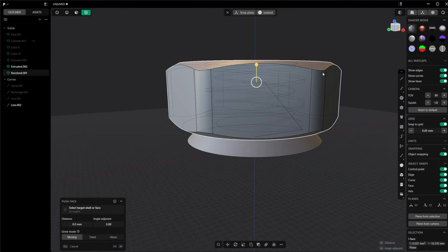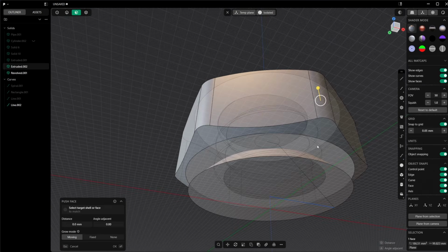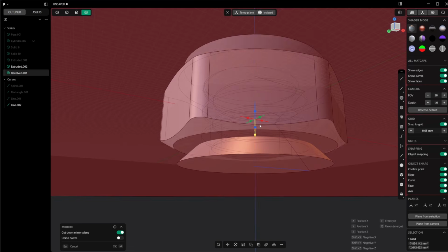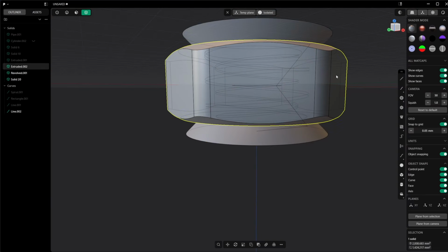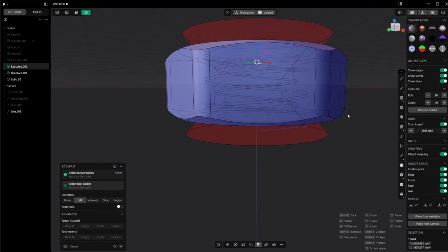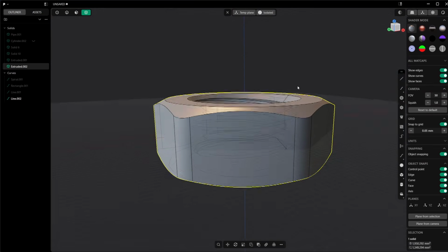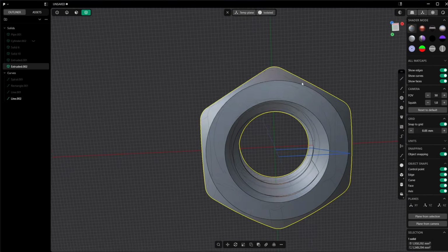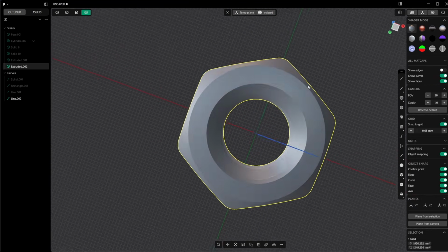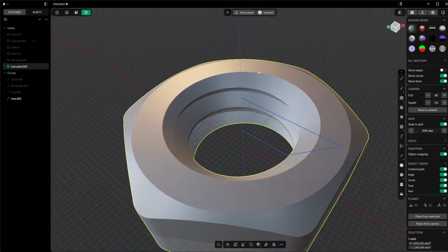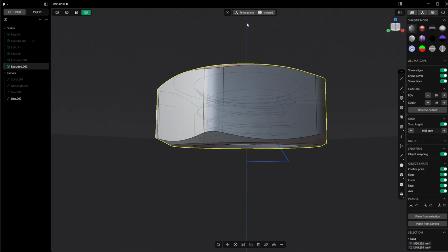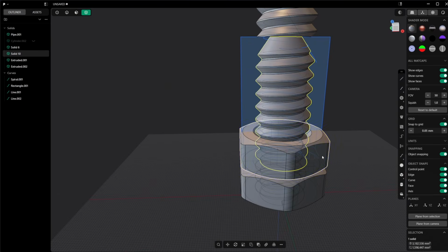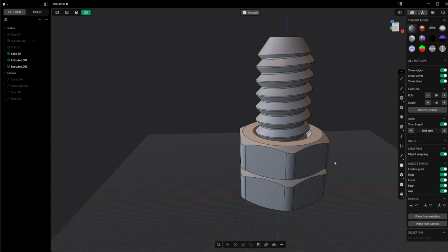I'm going to select this face and this face, Shift Space, select this one, Alt X to duplicate, and I'm going to duplicate it up. So we got 2. And then select this one, Q, remove this with Shift, and press Enter. And now you can see we got this nice bevel on this side and on this one side as well. So if I remove the edges, you can see it's not perfect here, but it's looking good enough. It's going to be very easy to insert. So if I remove that, go back from the isolation, now we got our nut and bolt system complete.